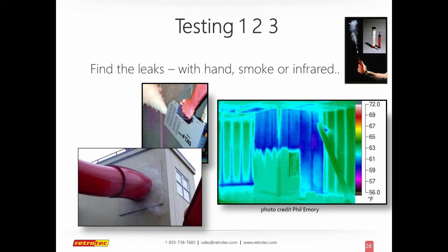This is a great slide that he uses, and it shows in the blue in the center clearly where they forgot to put insulation in, sections that are missing. We definitely have a heat transfer on the right side. You can see the studs plain as day. We have a blower door running right now, and on the left side you can see the feathering, and that's caused by air infiltration, totally different from a thermal connection. You also see it at the top, where air is coming in up through the studs and showing up on the ceiling itself.